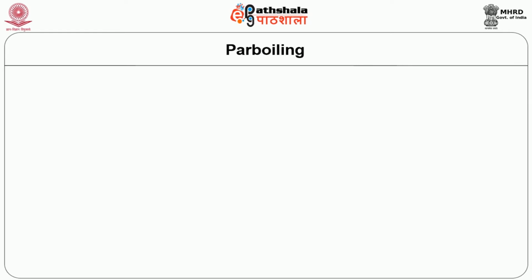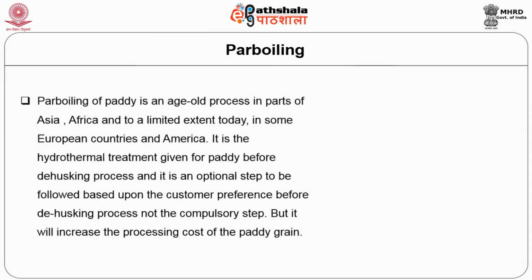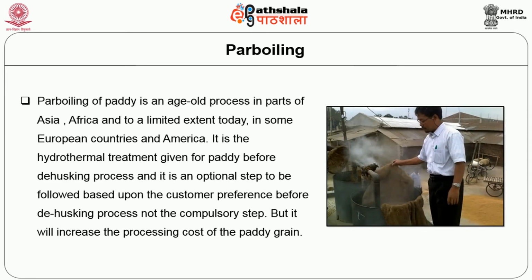Let us discuss parboiling. As I already said, it is the optional step followed in paddy processing. Parboiling of paddy is an age-old process in parts of Asia and Africa, and to a limited extent today in some European countries and America. It is a hydrothermal treatment given to paddy before the dehusking process, and it is an optional step followed based on customer preference, not a compulsory step. But it will increase the processing cost of the paddy.